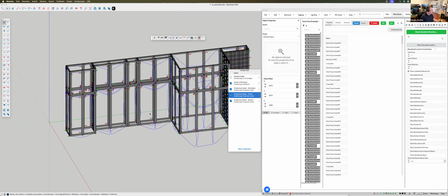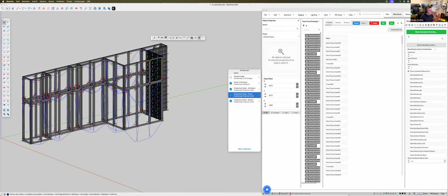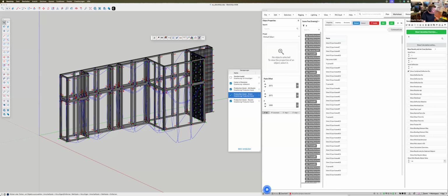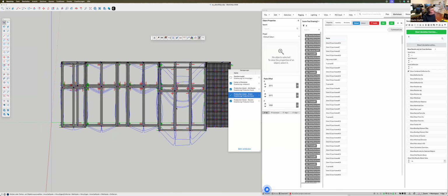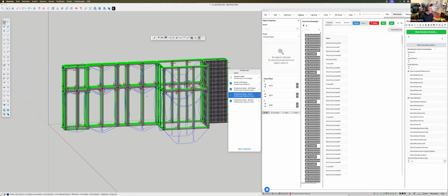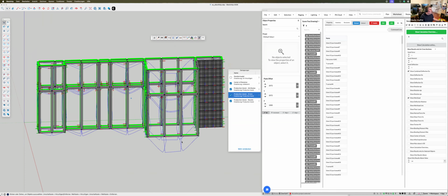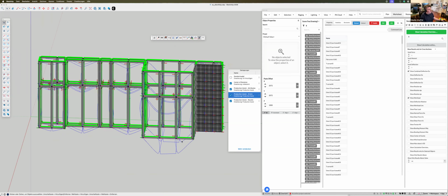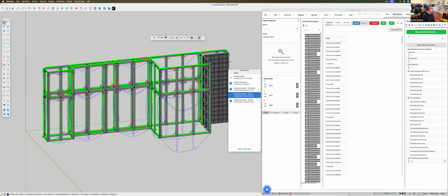Okay, with this, it can calculate this booth. It, for example, shows you the deflected shape. So how is this deflecting? Note this is a scaled view, so it's not deflecting as much as shown here, but it's showing you the scaled deflection. It also shows you the workload. If it's green, it means it's not overloaded. It calculates the forces on the ground and how much ballast you need for this kind of calculation. It also calculates all the different connectors that you have in here.